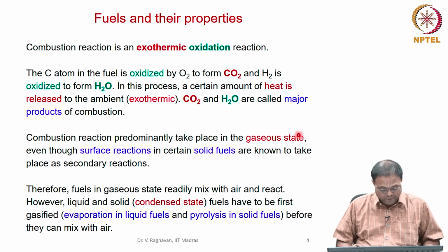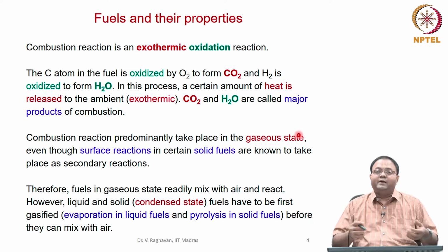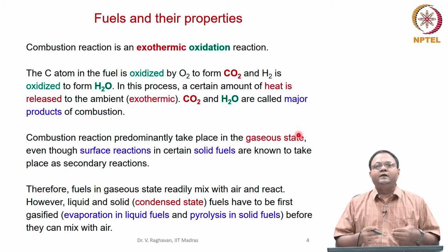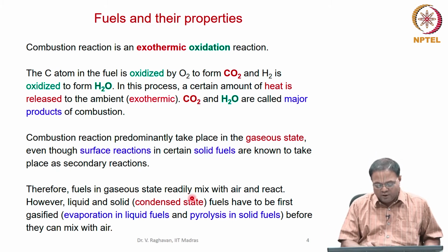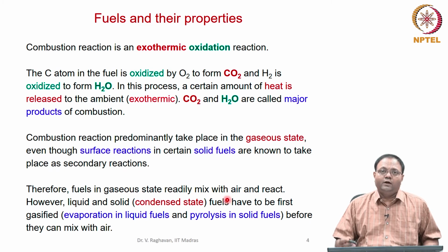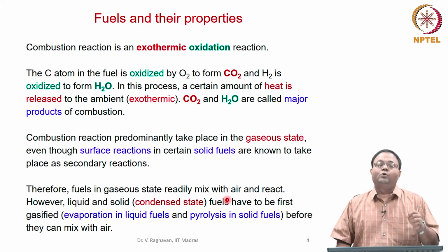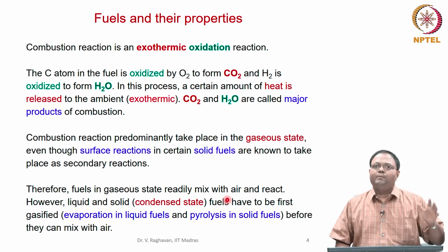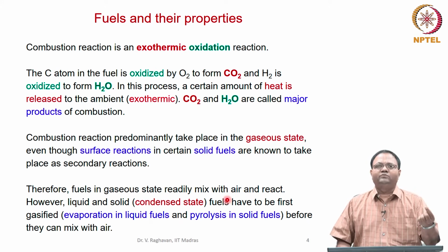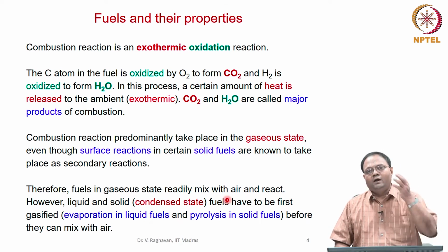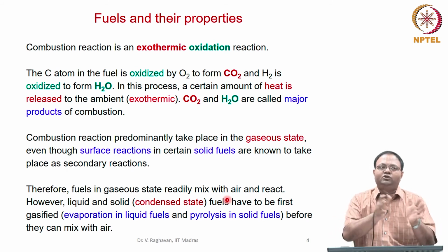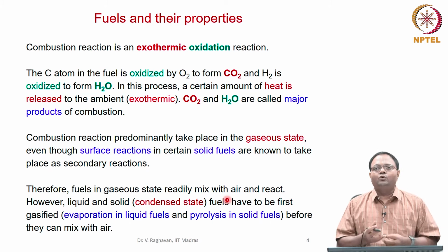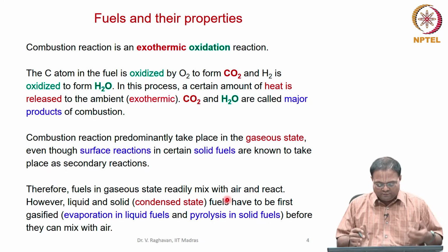So gaseous state. Now fuels can be in any state. This means we can handle any fuel, in the gas phase, liquid phase and solid phase. Fuels in the gaseous state readily mix with air and react. They should mix in proper proportions, though; any proportion is not allowed. For example, if you have only 1% of fuel and 99% of air, or 99% of fuel and 1% of air, it is not going to burn. That is the limit of mixing that will contribute to the burning process. Those things we will cover later.